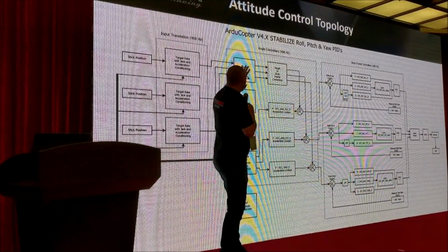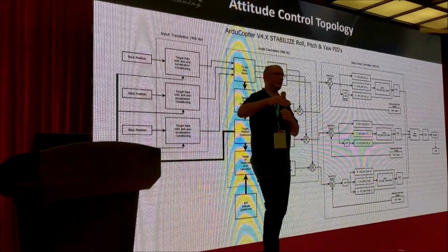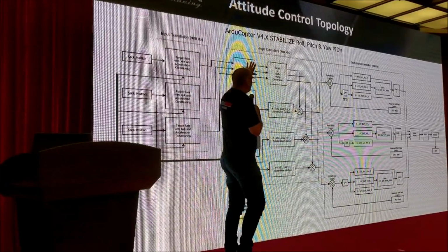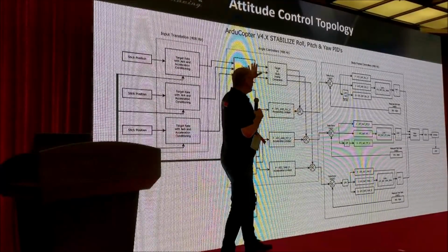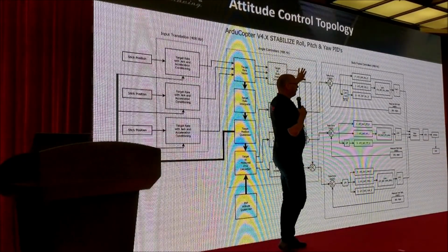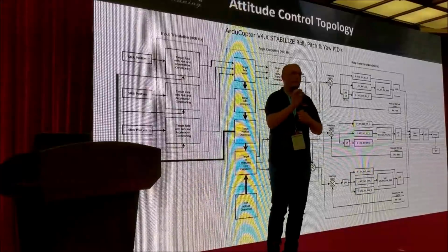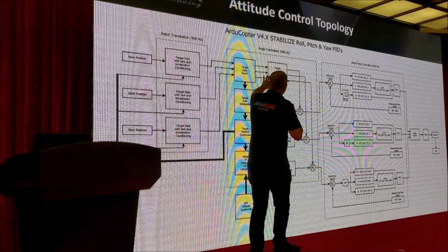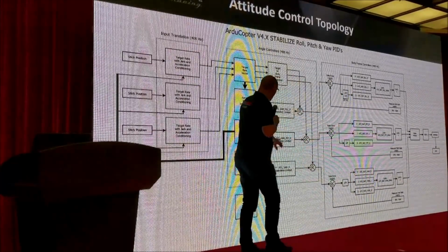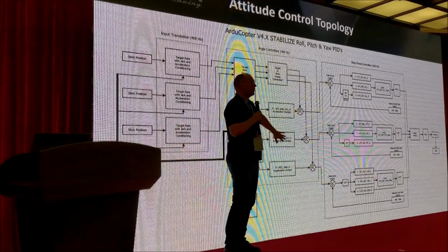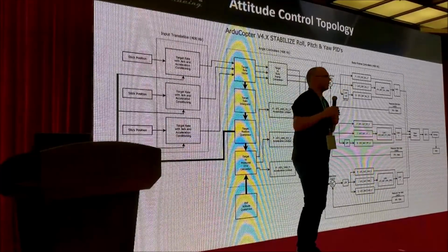So angular rate requests. And from these commands, we work out exactly what angle the aircraft should be at and what rate the aircraft should be moving to. We then have two separate streams. One of them is that feed forward rate command I was talking about earlier. Theoretically, if everything was perfect, this would be completely defining the pilot's input. But then here, we have the angular error components where the aircraft isn't quite where it should be.